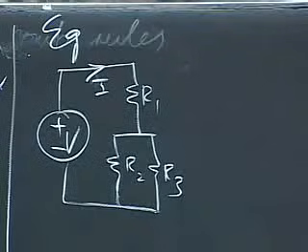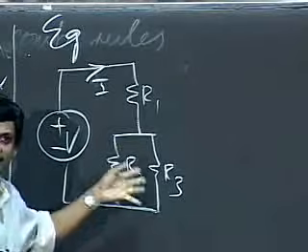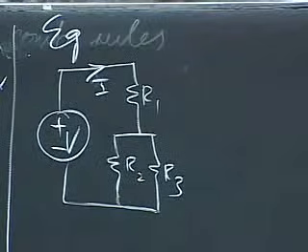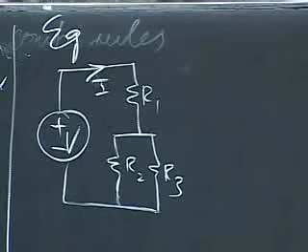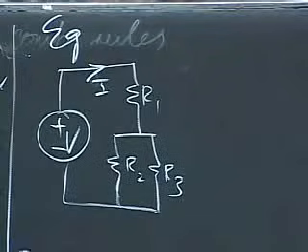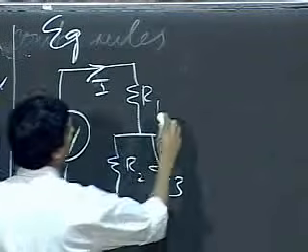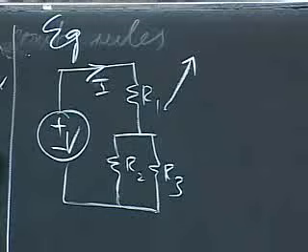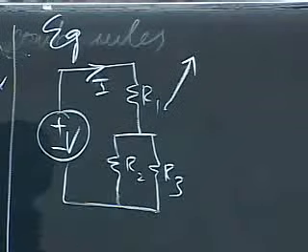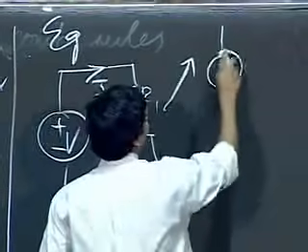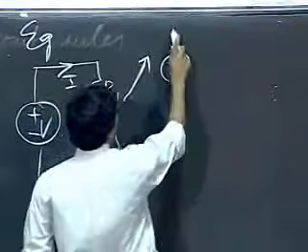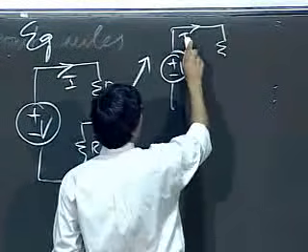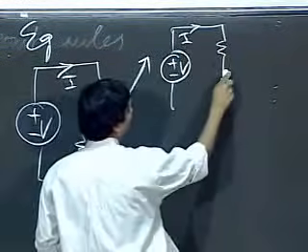Of course, you can go ahead and write KVL and KCL. You will get 4 equations, and there are 4 unknowns, and you can solve it. But I can apply my element combination rules and very quickly figure out what the current I is, using the following technique. So what I can do is I can first of all take this circuit, and I can compose these 2 resistances and show that this circuit is equivalent, as far as this current I is concerned, to the following circuit,